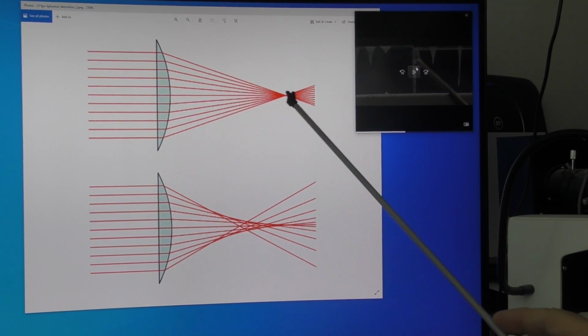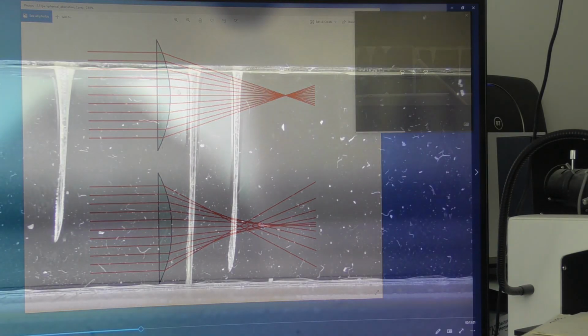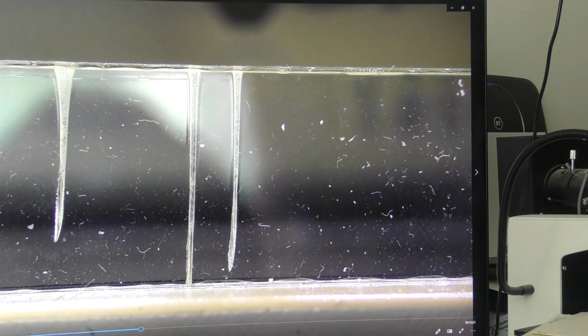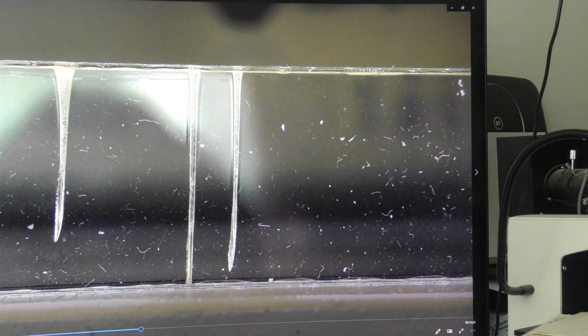We're still not at the focal point. This is just another type of mode burn. It's not a cut, even though it might look like a cut. There is no focus involved there. Then I set the beam to the correct focal distance. This is a 190mm focal length beam, remember. 70 watts, and this is a 1 second burn, and it burnt right through the bottom there.